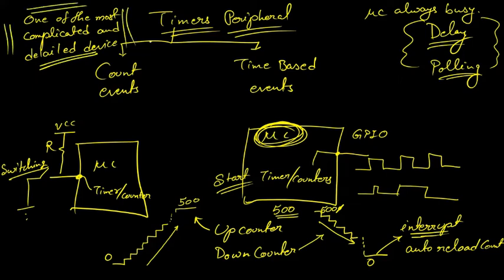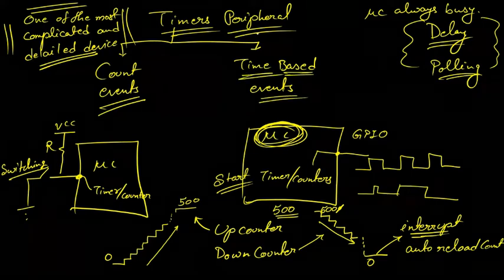There are lots of registers in these timers, and then there are so many bits to control to make a proper timer. But once a timer is set up, you don't have to worry. The microcontroller can go and do other jobs, or it can give its resources to other peripherals like ADC, DAC, or some other devices. So this way, timing related events can be managed by the timers. It can be counting based events or timing based events. Both are managed by the timers themselves.